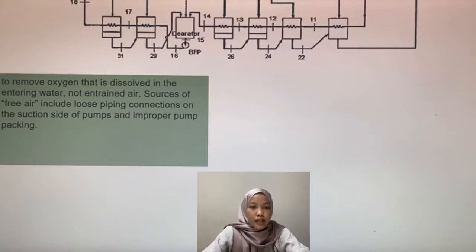Sources of free air include loose piping connections on the suction side, pump, and improper pump packing.